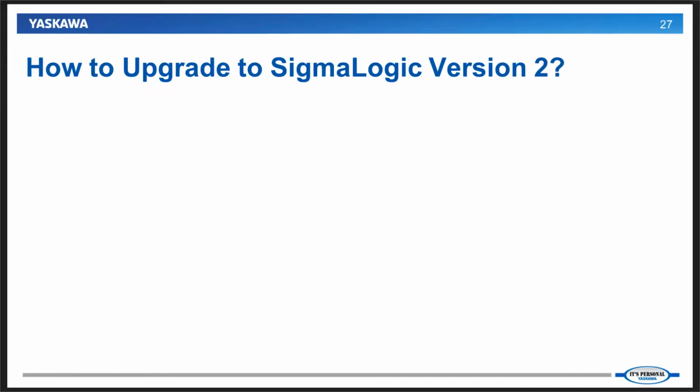So how to upgrade to SigmaLogic version 2? First, you have to make sure that your SigmaLogic unit is updated to firmware version 3.3. So if you have version 3.0 currently installed on your controller, then migrate to 3.3 using the web interface. You can update the firmware.